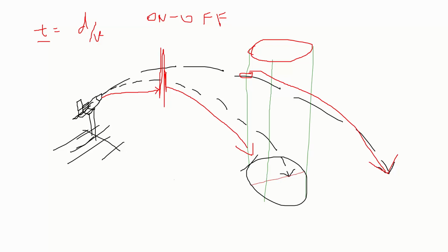So in order to make the rocket not only fall at its exact target, but also complete its course in a specific time period, we should have a controller that firstly moves the rocket at high speed, then when it closes in on the target, its speed keeps on reducing constantly. This is similar to the approach where you apply brakes while driving when you see a red light ahead. This type of control is possible by using derivative control along with proportional. So we'll talk about this PID controller later.